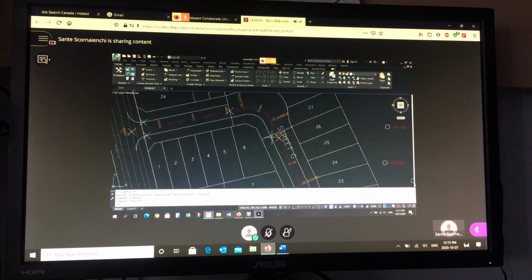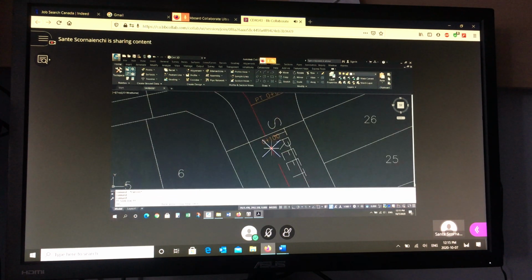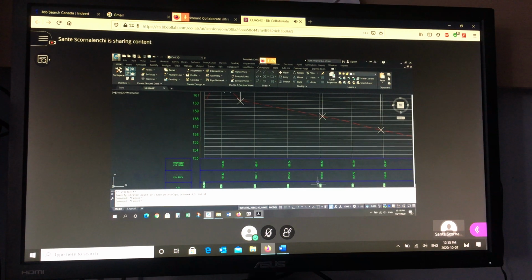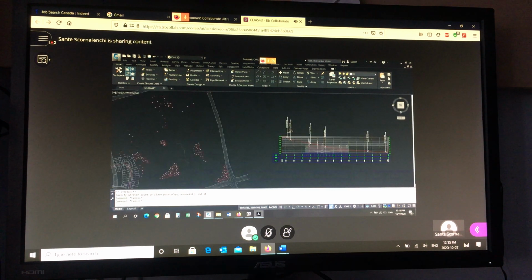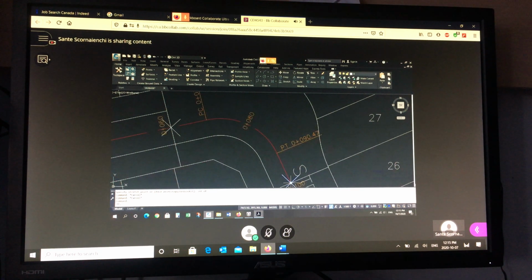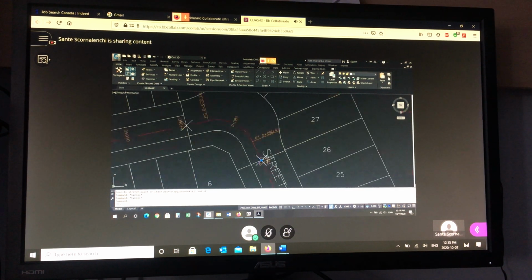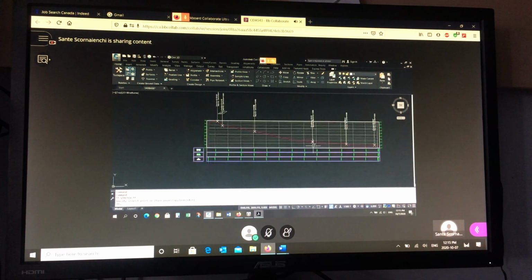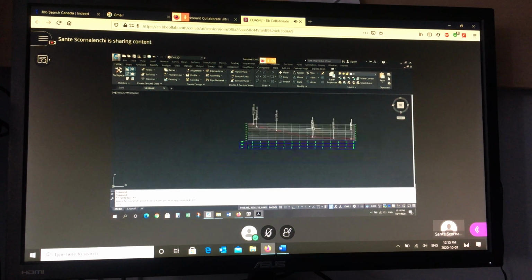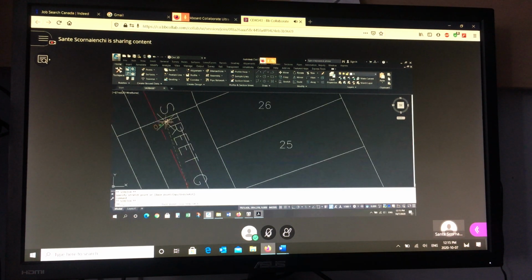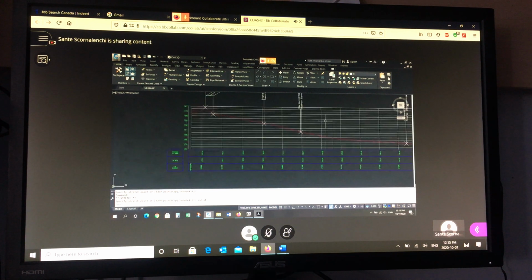If I move this point in the plan view, it actually moves it in the profile view because it's projected. It's dynamically linked. So if you have to redraw the elbow, just keep this point. Once you move this, watch. Let me put it way over here. Right now it's way over here. If I move it back, it'll be closer to here. It's dynamically linked because it's constantly projected. Right, and that moves it closer.